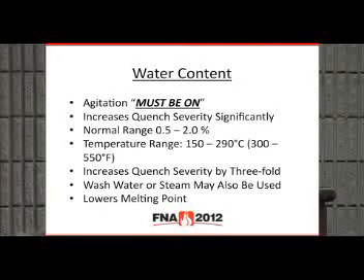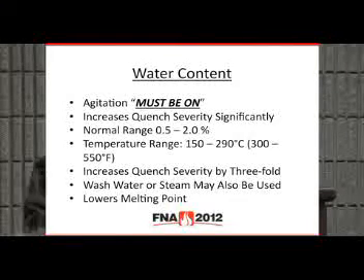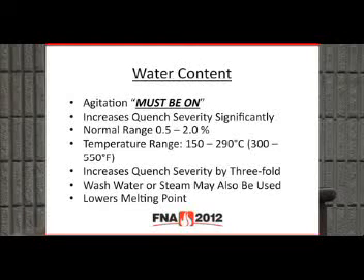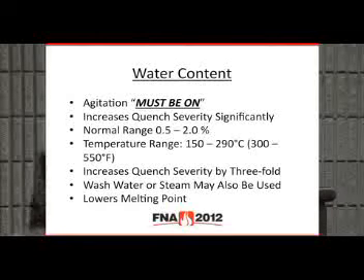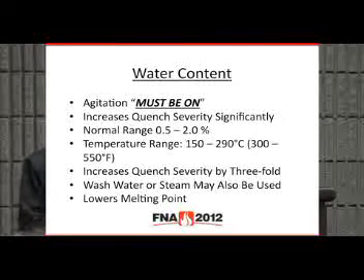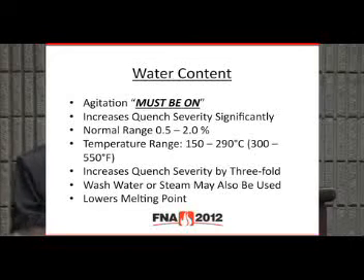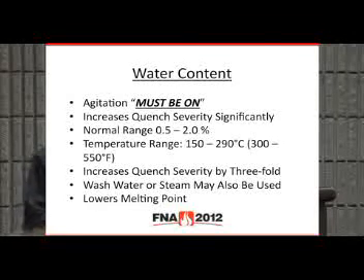Water content, as I mentioned, agitation should be kept on from a safety point of view. It increases quenching severity significantly. A normal range of water content is 0.5 to 2%, depending on the operating temperature, and it can be used in the range of 300 to 500 degrees F. At higher temperatures, the solubility of water in salt decreases significantly. At 600, I think it's maybe 0.25% or something like that.